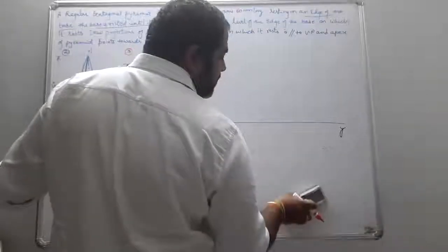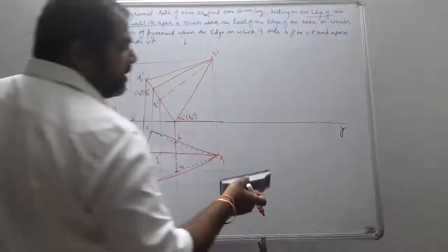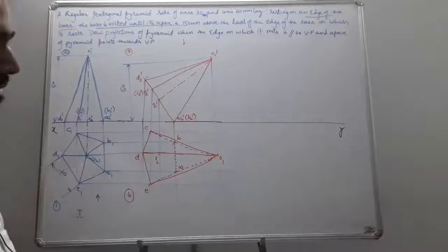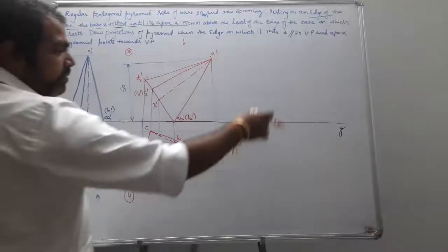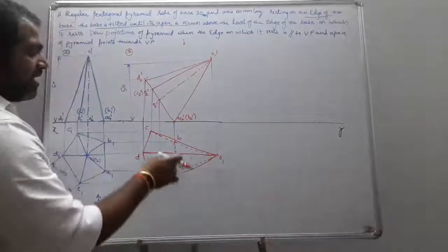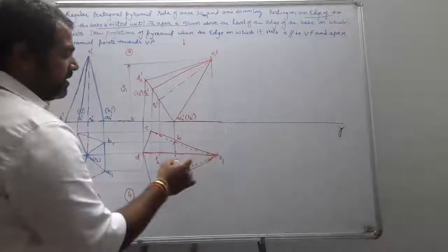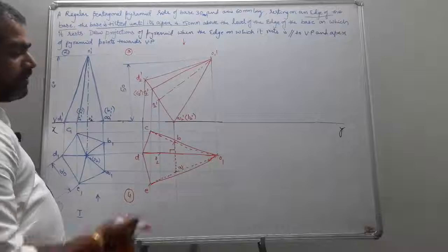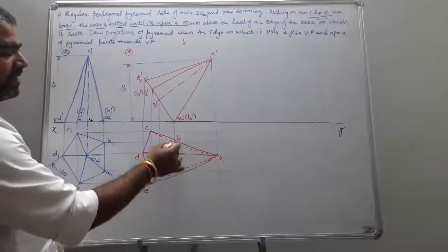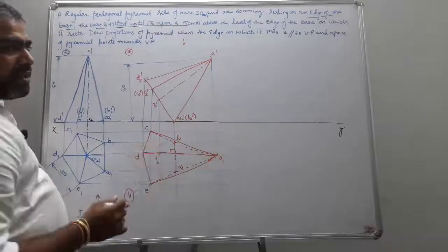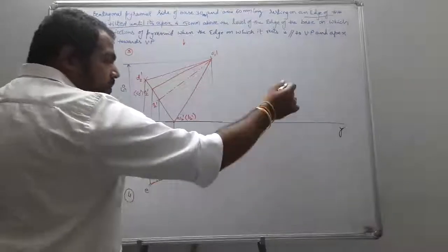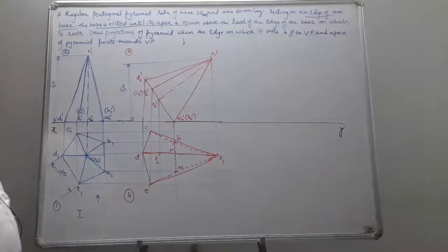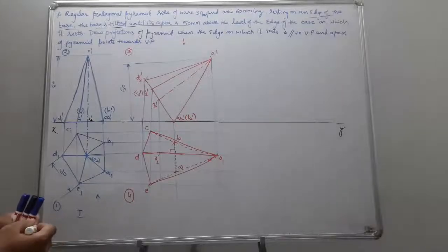Students, the change of position method, I think all of you know. Further, I am not constructing the change of position method. So you just reconstruct the figure in such a way that this O1, O2 becomes perpendicular. Then BA becomes horizontal. Let us see, these two are perpendicular in general. So your requirement is that the BA edge becomes horizontal. How does it become so? If you take O1, O2 perpendicular to XY, simply.